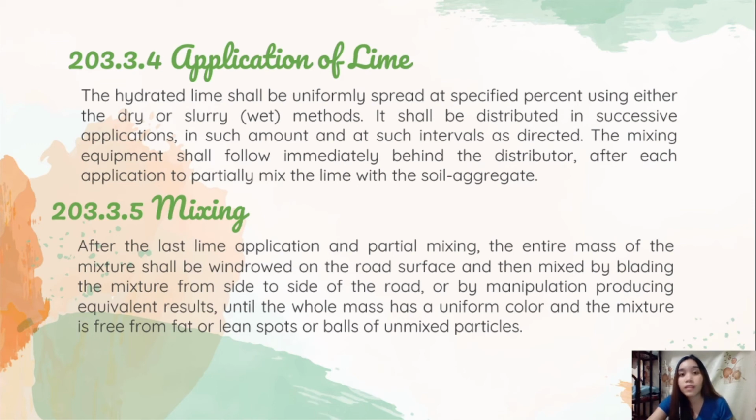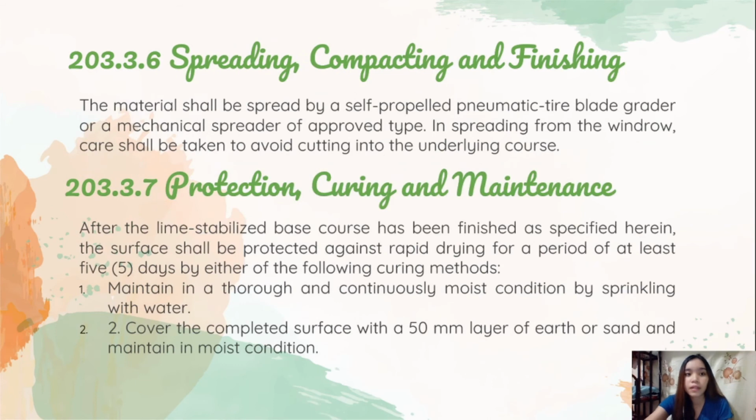Then when directed, the mixing process shall be confined to part of the width or area of the road so as to allow traffic to pass. And then when the mixing operation is complete, the mixture shall be conformed in a windrow of uniform cross-section.